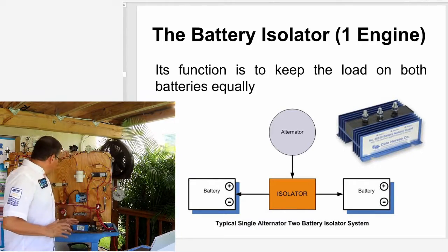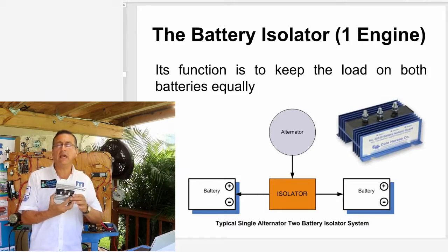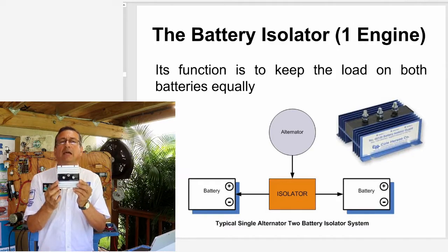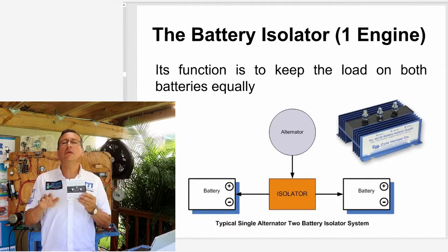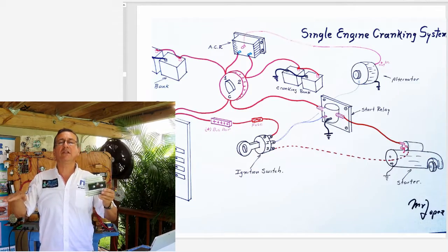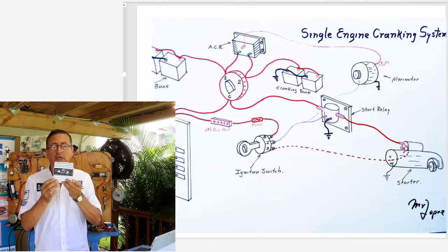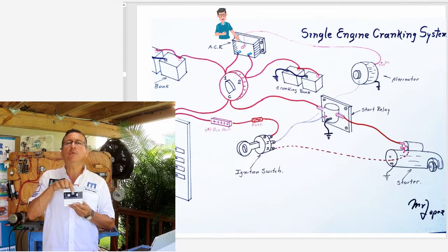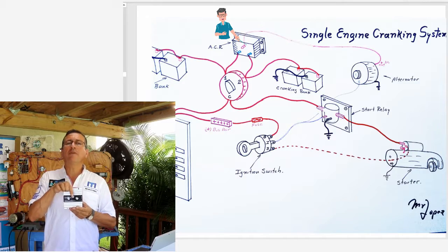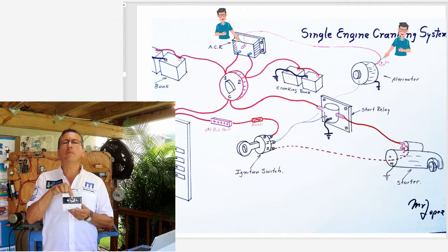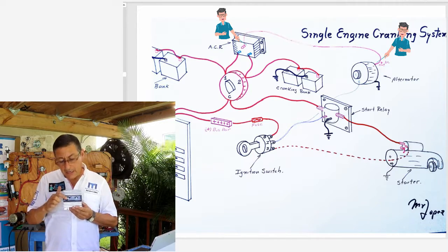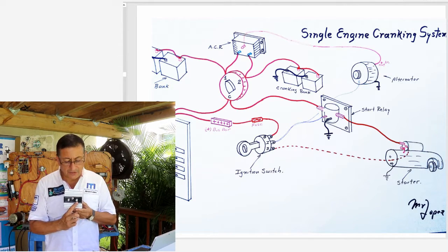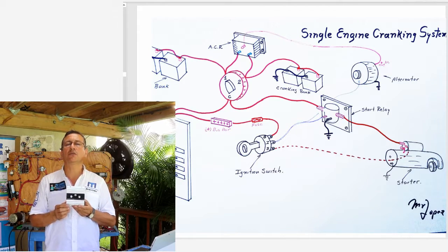There are different types of automatic charging relays. This is the ACR. The ACR is a device, an electronic device used to keep the charge of both battery banks stabilized, equal. In this particular case, this battery charger has one input and two outputs. The input is the power coming from the alternator, or the power coming from the battery charger. And this is the output connected to the positive of battery bank number 1, and this is the output connected to the positive of battery bank number 2.